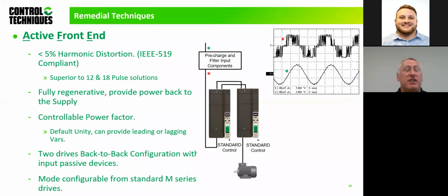It's fully regenerative. The other good thing about it, it has a controllable power factor. So unity is the default, but you can put leading and lagging VARs on there if you needed to, just to correct the supply. But again, if you are looking to do that correction, of course, you've got to remember the resultant size of the drive is going to be bigger, okay? Because now you're trying to provide VARs to the system. And as I said, this is a standard product from Control Techniques, along with some additional external filtering components.